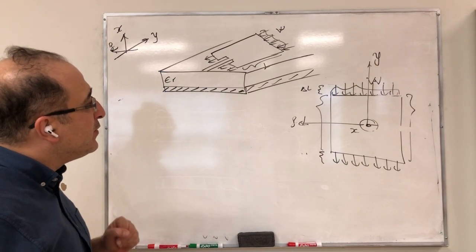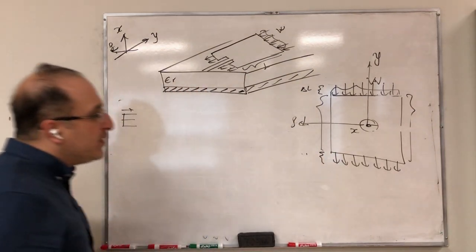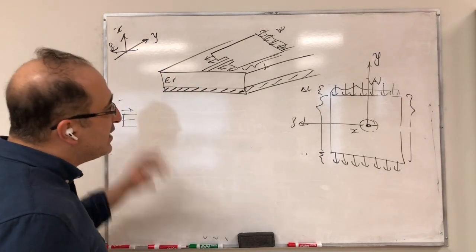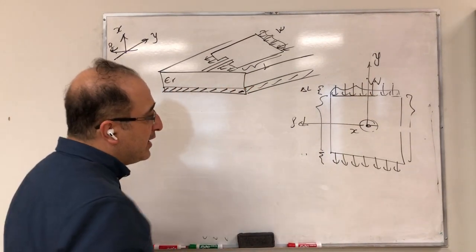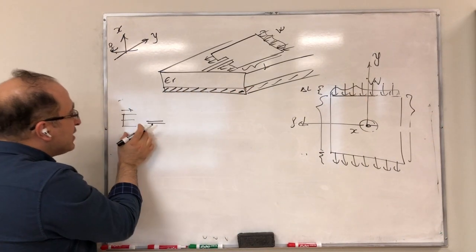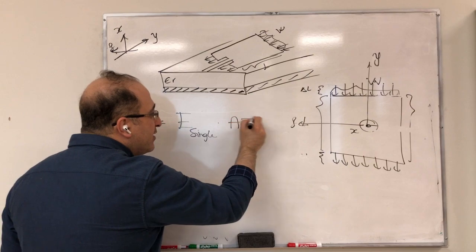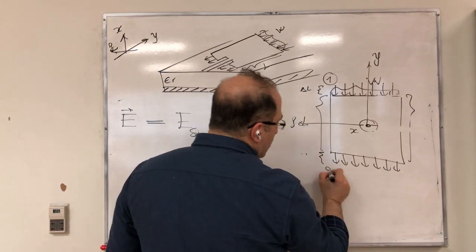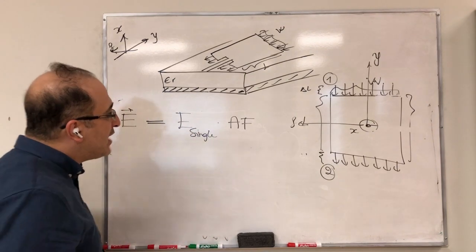But imagine you want to look at the electric field of this antenna system. Then perhaps you could identify one component in this electric field. Remember, I said you can think of that as a two-element antenna array. So if you have a two-element antenna array, you can say the electric field is E of a single element multiplied by the array factor. The array factor is for a two-element array, number 1 and number 2. So you have a system like that: this is your single element times the array factor.